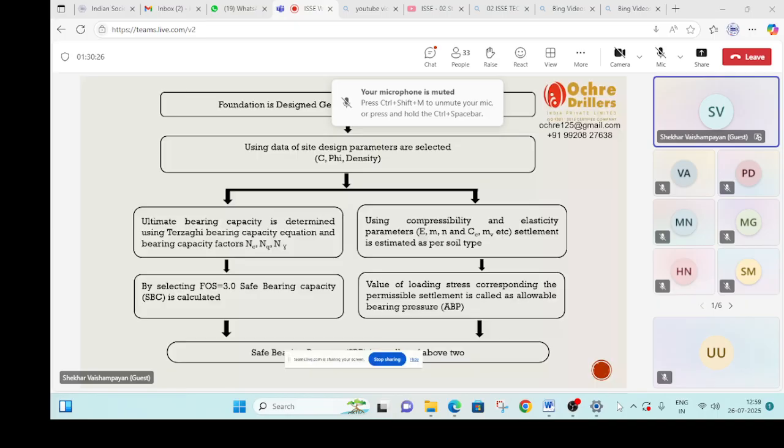Using the load increment, what you are planning to put on the structure or the foundation strata, you estimate the likely settlement. If the settlement is within your permissible limit, that is a limit permitted by the structural engineer or structural design, you know the limiting values 1 in 250, 1 in 550. Normally the limiting differential settlement is 1 in 500. That is the best value which is normally taken for very good performance of high value finishing.